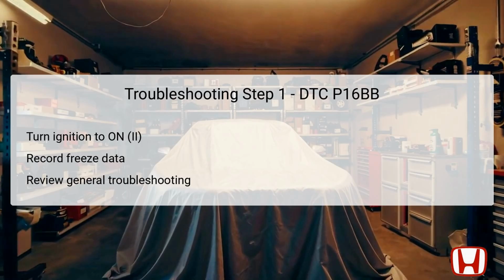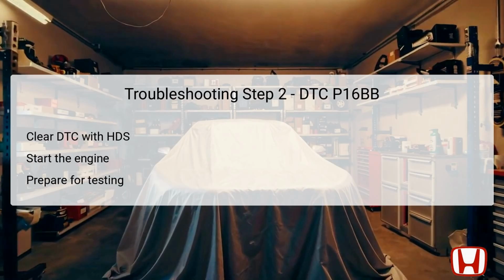For the second step, utilize the Honda Diagnostic System (HDS) to clear the previously recorded diagnostic trouble codes. By clearing the codes, we will effectively reset any stored faults in the Engine Control Module (ECM) or Powertrain Control Module (PCM) prior to further testing.